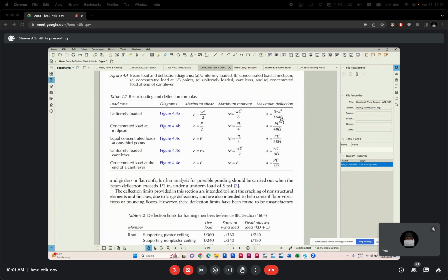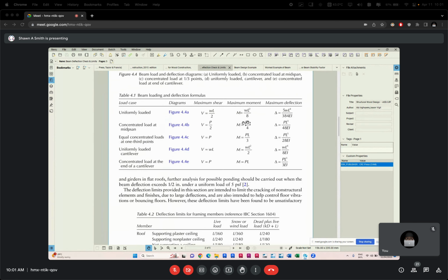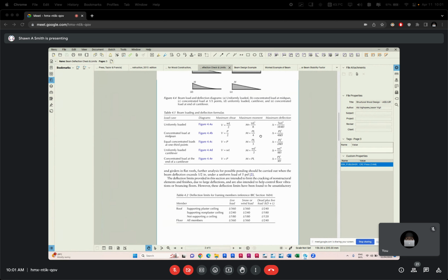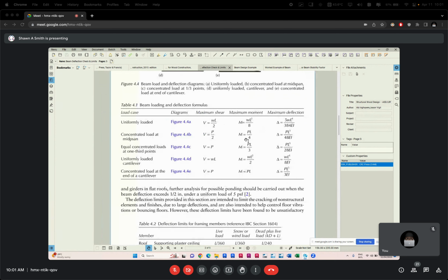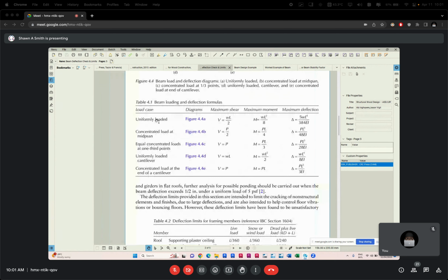Last week, we looked at moment of inertia. We are doing simple rectangular beams or square beams. It is BD cubed over 12. We have gone through that. I is BD cubed over 12, and that comes out in inches to the 4th power. All right. So we are, for the most part, in this particular scenario.